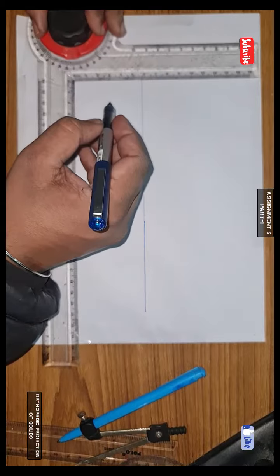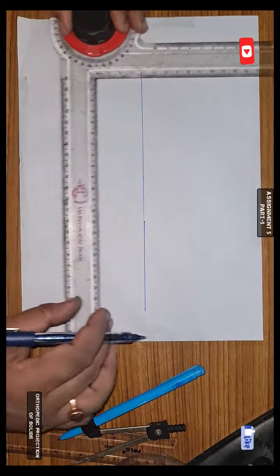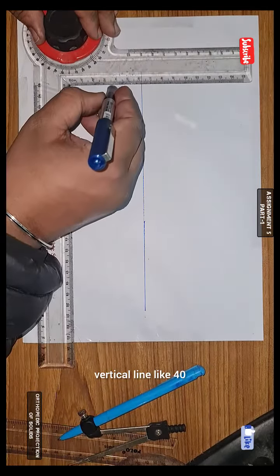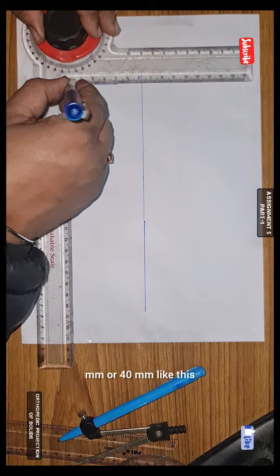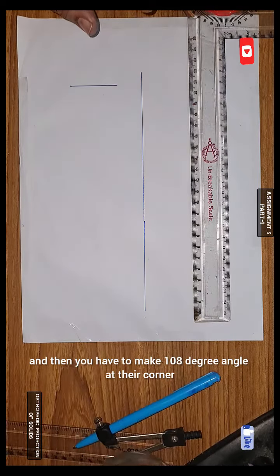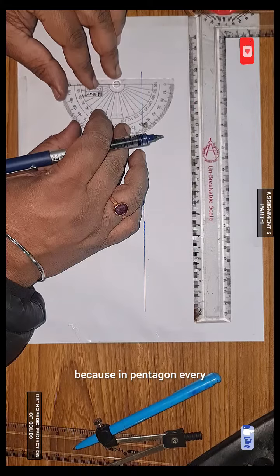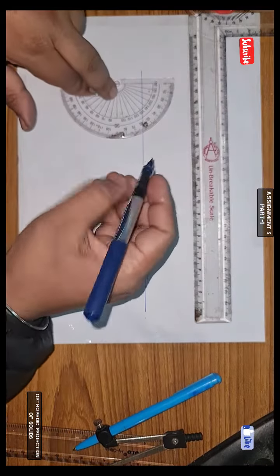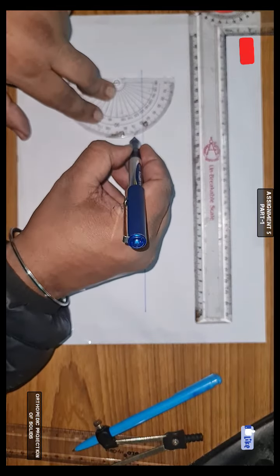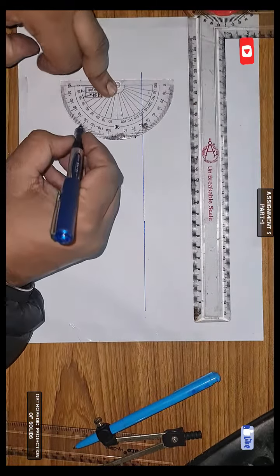So if it is 40 like this, you need to make a vertical line like 40 mm like this, and then you have to make 108 degree angle at their corner, because in pentagon every internal angle is 108 degree like this. This is 108.